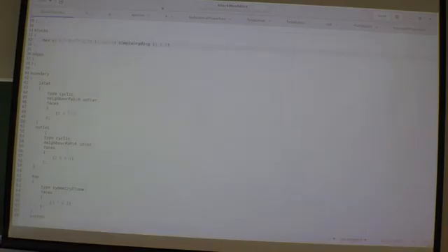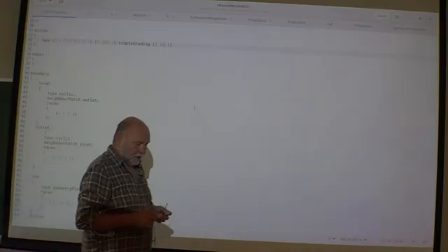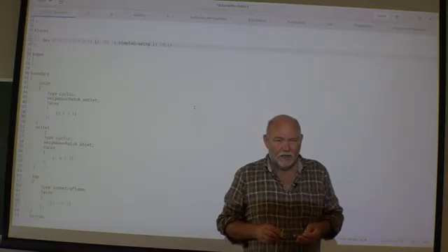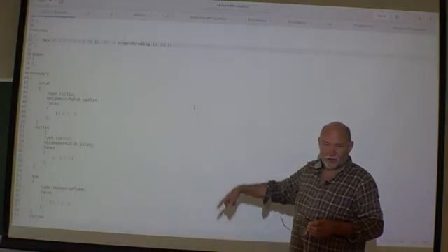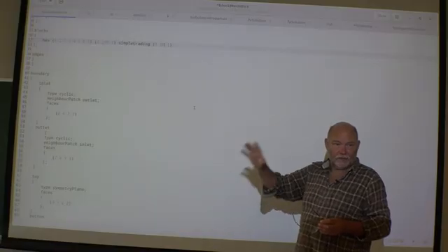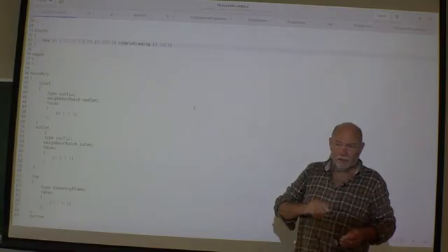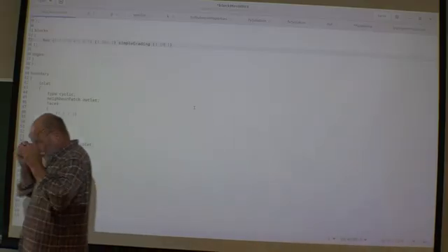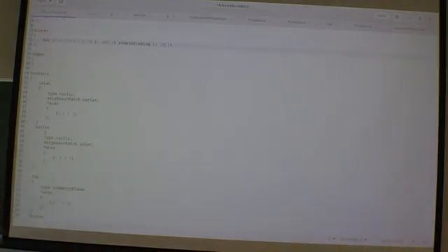So what should we change then? We can stretch the mesh a little harder. I use 10. Okay. Now, here is one point. Remember what we are going to do afterwards with the result here. We are going to use them as input files, as inlet conditions in another simulation. Then we should have used the exact same mesh in the y direction as the original that we are going to use later. But here, never mind that. I just want this simulation to be okay. So I save this one.